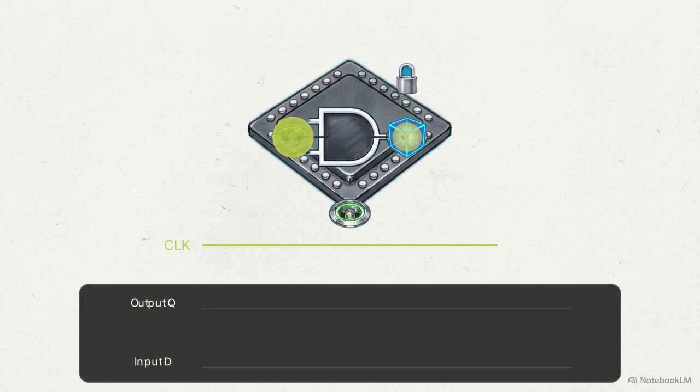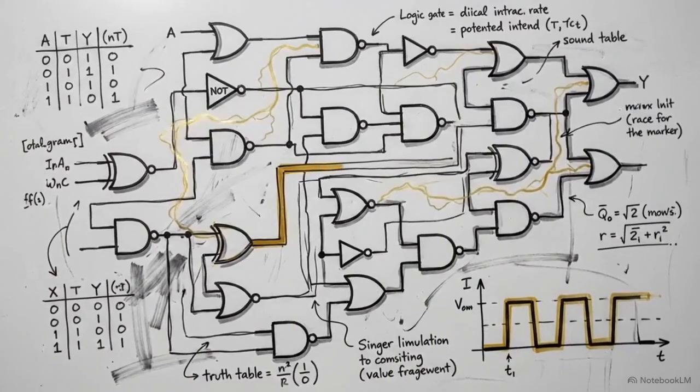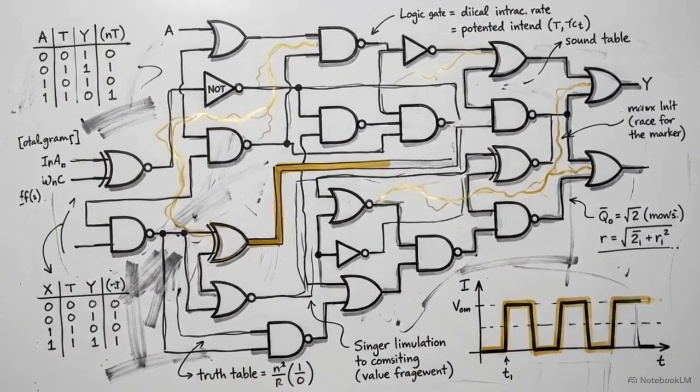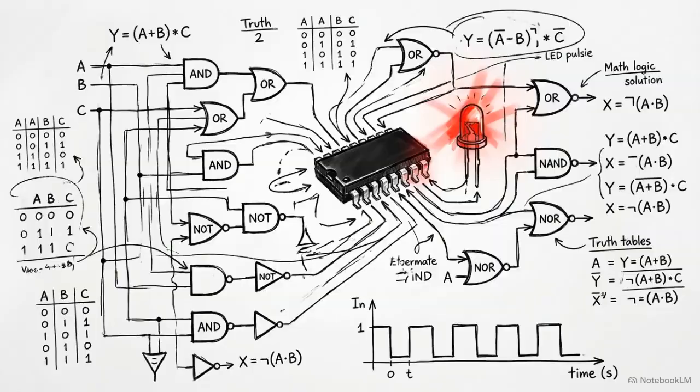This timing chart traces the result. While the input lines fluctuate, the Q output maintains a flat line, holding that 1 over time. In digital electronics, memory is a specific electrical state held static by the precise timing of a clock pulse. This physical D-type flip-flop holds exactly 1 bit of data.